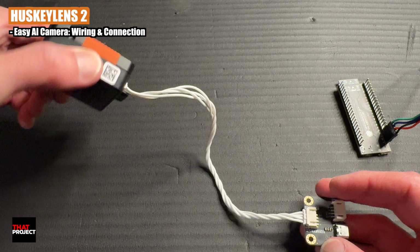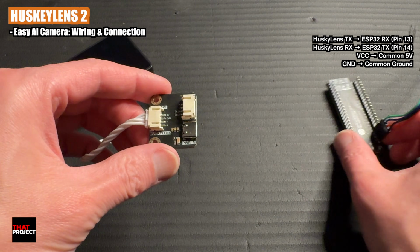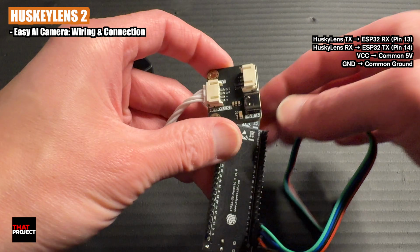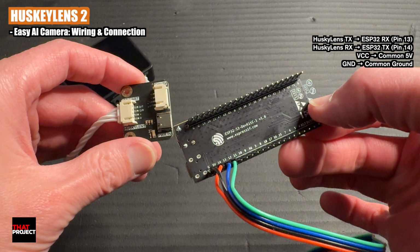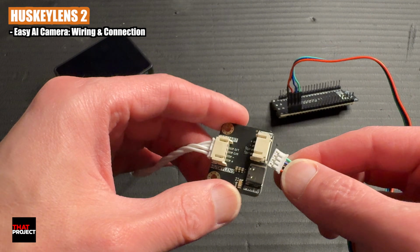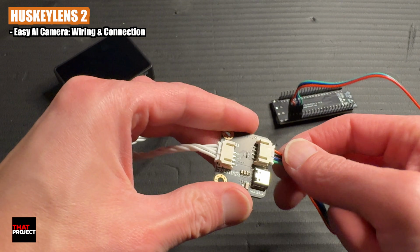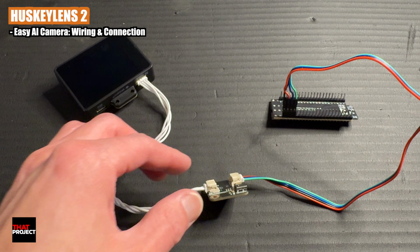For the controller, I'm sticking with my old reliable, the ESP32-S3 DevkitC. It just works perfectly for initial tests like this. I have connected the usual suspects: RX, TX, ground, and VCC. One small detail to catch: this breakout board doesn't actually output 5V back to the ESP32, so I did have to run a separate 5V line to power the camera board directly.